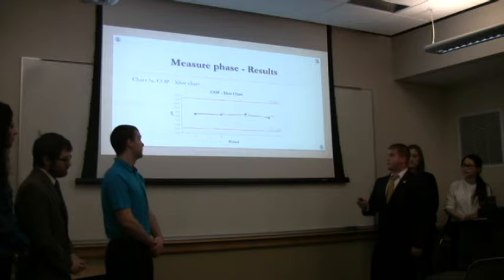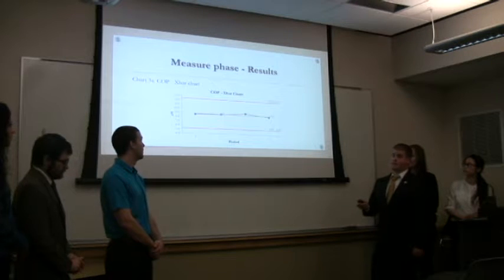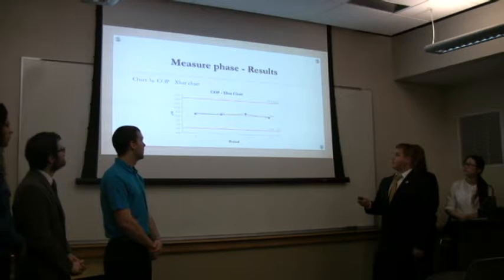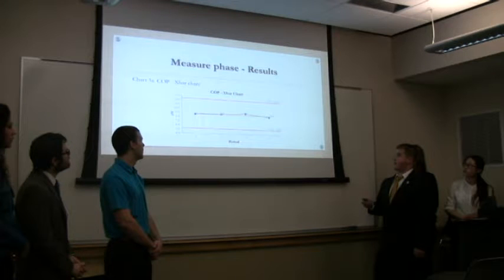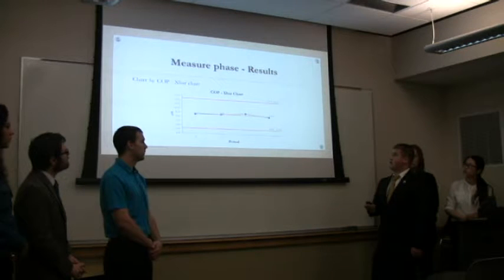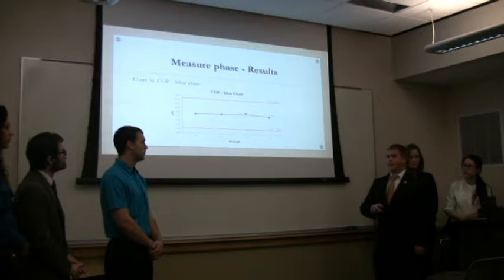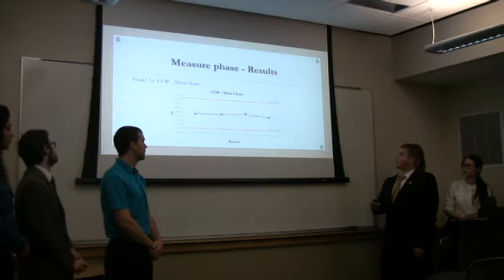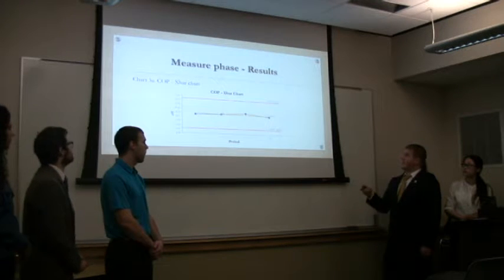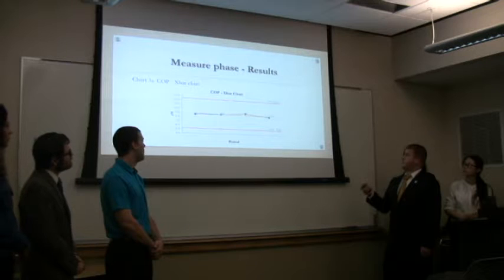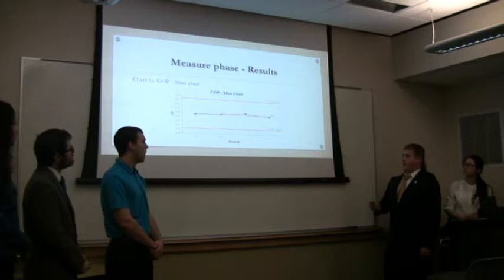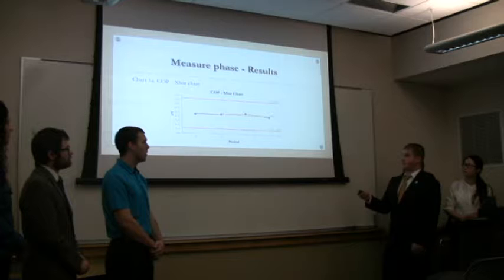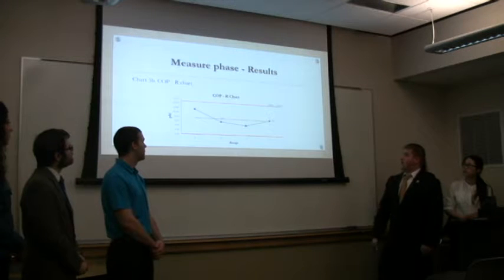Our COP was much more accurate, or I should say precise, in that most of the averages hit right around the center line, which is about a 9 pH. The biggest difference I want to point out with this X-bar chart is that the control limits are much wider. So we had a little bit more of a range on our samples, which we'll see in our R chart.